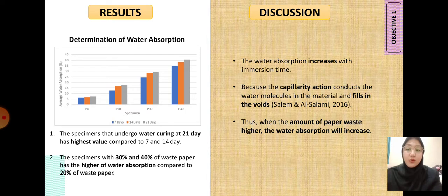The figures show the percentage of water absorption. The specimen that underwent water curing at the 21st day has the highest value compared to 7 and 14 days. The specimens with 30% and 40% of waste paper have higher water absorption compared to 20% of waste paper.